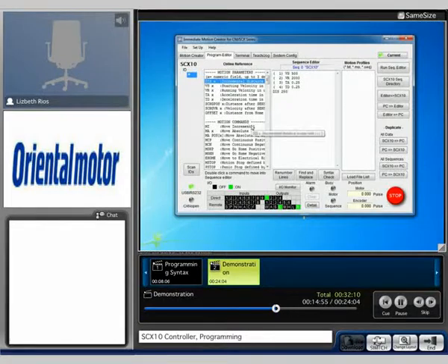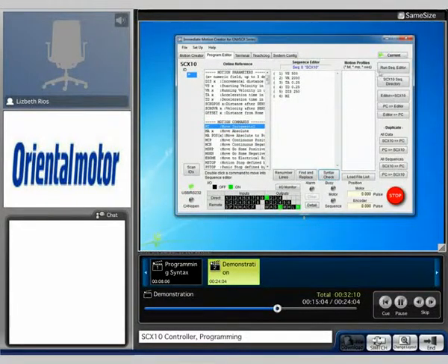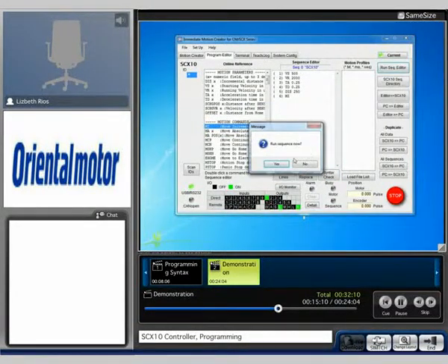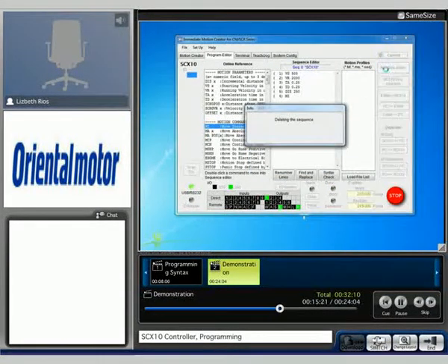Then we need our motion command, which is move incremental. We can renumber our lines and do a syntax check. Then we can select the Run Sequence Editor, which will run our new sequence. So we should see the motor position and encoder position at 250 pulses. And I'm going to go ahead and rerun that.